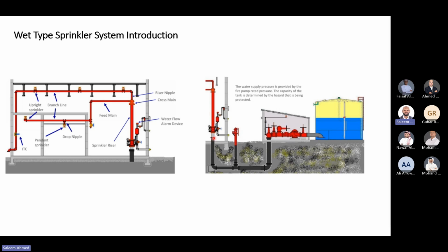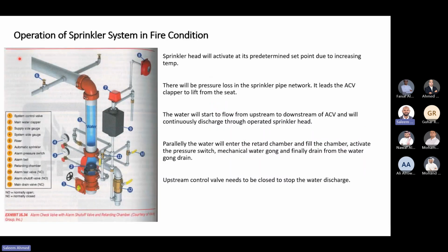If you go here, you already charge the water here and you shut off the pump. Then if you don't have this check valve, you assume the black one is not there, the water will drain back, and the water will not be stable. In order to prevent the backflow, you are having that.